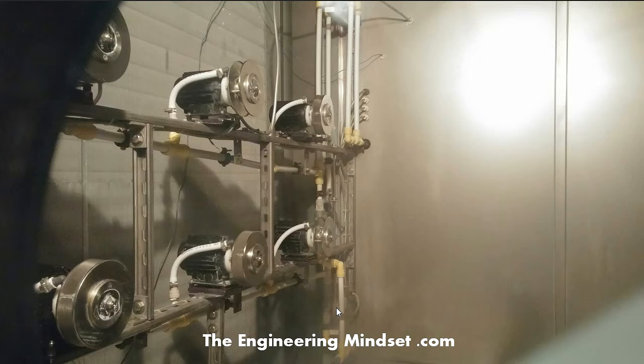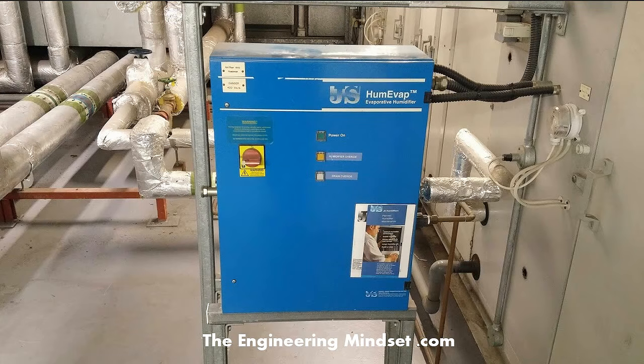So this is a humidifier here. It's got water coming in and it's just spraying this out. These small induction motors are spraying that water out in a very, very fine mist. As that sprays out and creates the mist, that's what adds humidity to the air and increases the water content of the air. Another way to do it would be through something like this, which is an evaporative humidifier. You can go for a steam system as well, so there are many ways you can add moisture to the air, and it depends on whether the environment is critical or not.